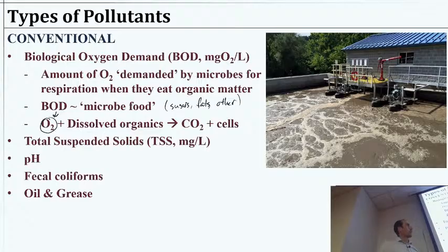Next up would be fecal coliforms. This would be an indicator bacteria for fecal contamination, so we call them fecal coliforms. The way we measure them typically is we would just say any type of bacteria that can grow under certain conditions, maybe with some media on a petri dish, when we incubate it at a temperature that is typical of a warm-blooded gut. It doesn't necessarily mean they are fecally related, but there's a good chance. So we make that kind of a count, and we say, all right, well, we have this number of these microbes per liter, and so we have some concern.